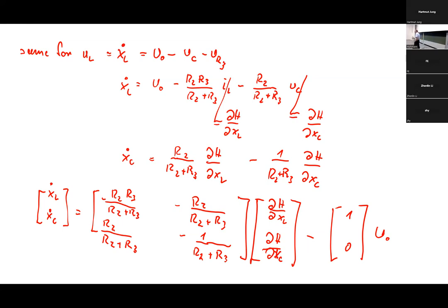Is it possible to deduce from every given equivalent circuit or bond graph a port-Hamiltonian system automatically? And the answer is yes. Fortunately, you can believe me, it's possible. But we see it's not always possible, because we need this linear resistive structure, we need something to solve for, and there are some intermediate steps which need some careful attention.